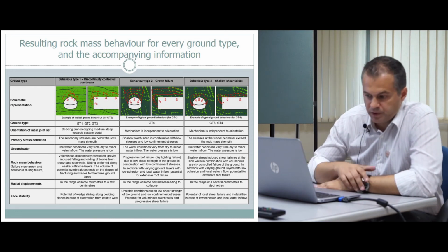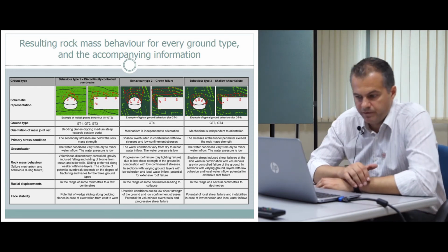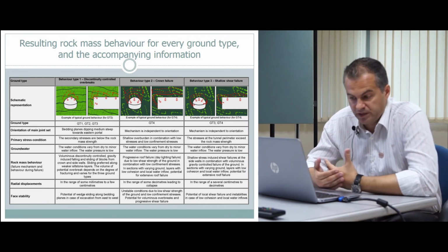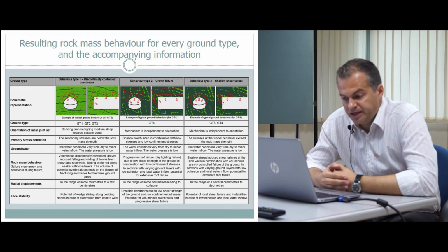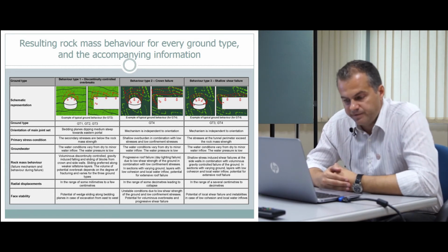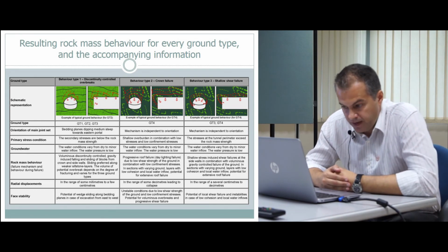The volume, of course, of the potential overbreak depends on the degree of fracturing and varies across the three ground types. So an underground wedge analysis will be executed in order to calculate in detail these volumes and the safety factors of this case.